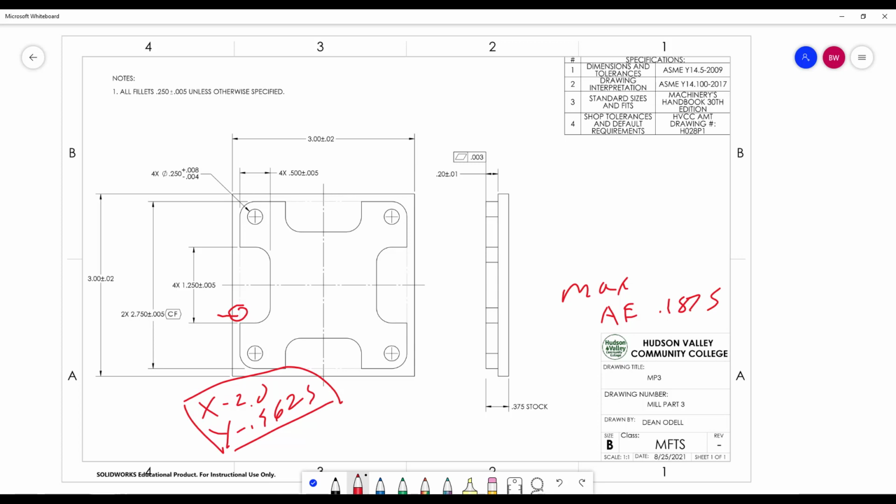All right, so let's take a look from the center of the part, which is going to be our work offset. Sorry, I hope I was clear on that. We are going to work 0, 0, because that's where all the numbers come from. So this is work offset. Okay, we're working with the center, and actually what I'll do is I'll just change color here to something green. Okay, green equals G54.